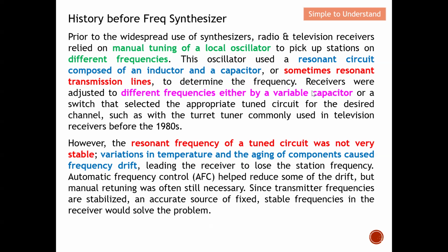So when we actually change the capacitor, the frequency also changes. So this is how we generated different frequencies before frequency synthesizers existed. However, the resonant frequency of a tuned circuit was not very stable. Variation in temperature and the aging of components cause frequency drift.